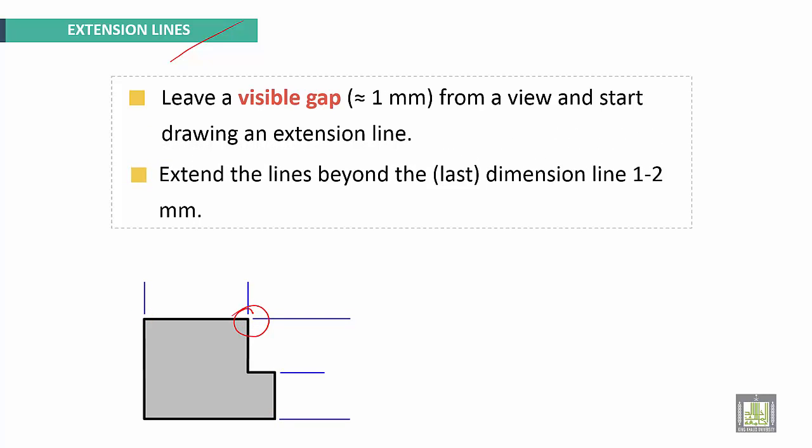Okay, extend the lines beyond the last dimension line 1 to 2 millimeters. Extend line here and here 1 to 2 millimeters. Here also this small extension.